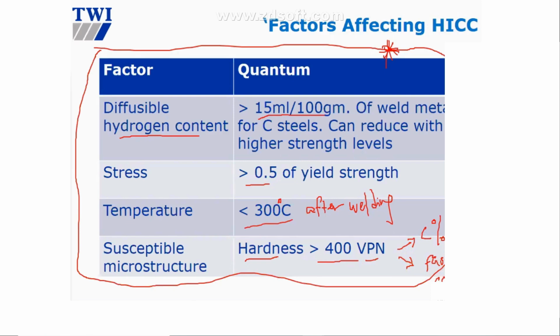After welding, for example, very fast cooling after welding with a very high percentage of carbon, right? So that you get very high hardness. And the microstructure, what is said here, is always martensite. When you get high hardness, the grain structure has changed to martensite. Yeah? Fast cooling, for example, you get martensite grain.